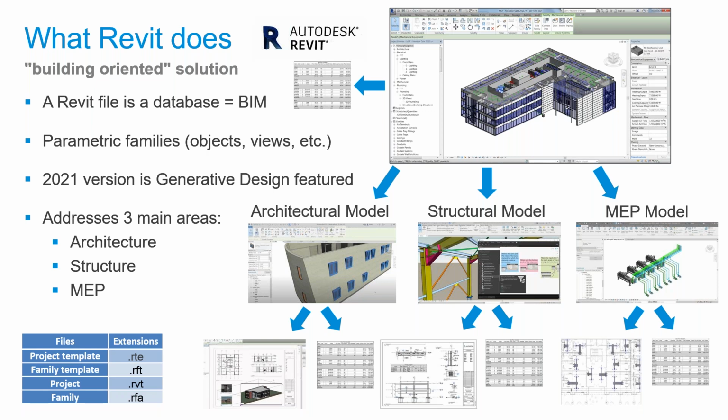All the entities within Revit are parametric, whether they are families or views or others. You will use it in Revit very efficiently, and everything is computational, and you can even use Dynamo, since a few releases ago. You can play Dynamo with the Dynamo player within Revit, and the recent release of Revit 2021 has an embedded generative design feature.